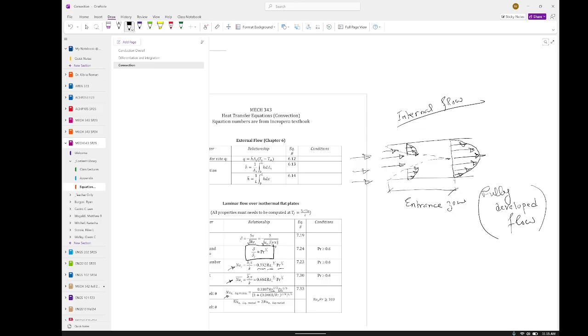That's pretty much it. There is no more fundamental theory I was going to cover. Now, this is the fluid boundary layer that I covered. The heat transfer boundary layer acts the same way. You have learned it in external heat transfer. You remember external flow? There is a relationship that gets established by a number. Which number dictates the relationship between the thermal and hydrodynamic boundary layers? The Prandtl number. Remember the boundary layer thickness? You've done it in one of the homeworks, right? There is a ratio, and that is dictated by the Prandtl number. Same thing here. It's nothing new.